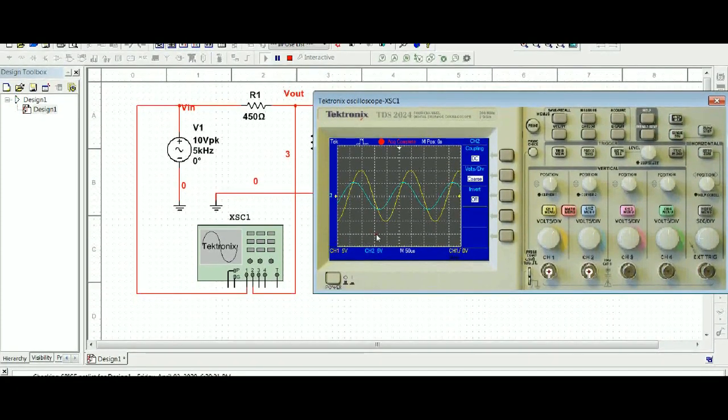Now just taking a look at this circuit, what I see is my yellow waveform, which is our input, is pretty much perfect, 10 volts, and my blue waveform looks to be a little bit over 5 volts. So if I want to, I can pull cursors out to measure that, and let us do that. So I'll click on cursor, and the type I'm going to start with is a voltage cursor. Now notice that the lights are on here next to cursor, which means those are no longer position controls. So I'll start to bring out a cursor here, and I'll bring it up to the bottom of our source voltage, and what I'm seeing here is that the cursor is at negative 10 volts.